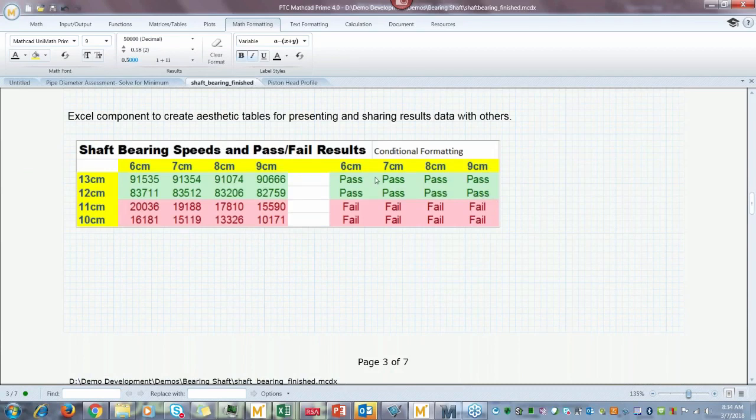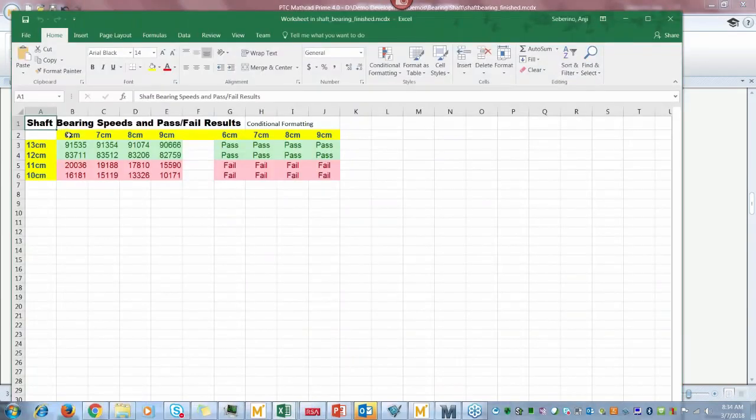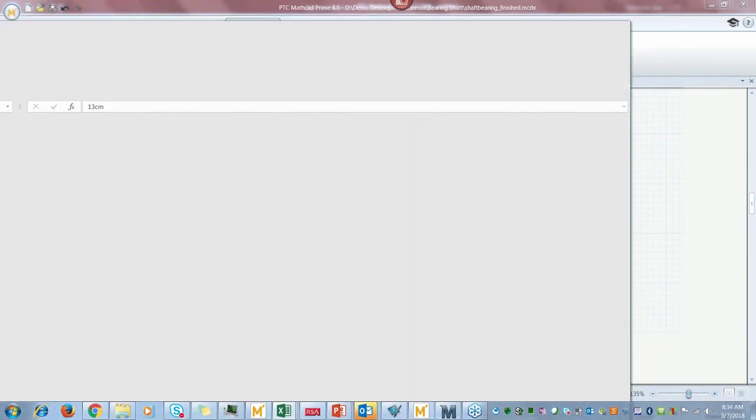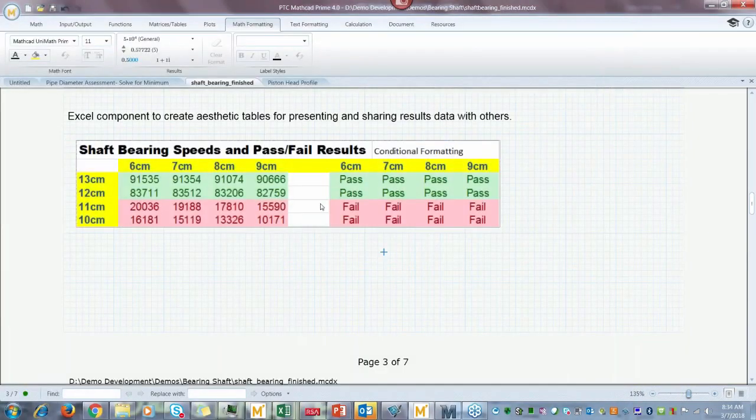And when I did this, here's Excel, I manually wrote in these diameters. But what I really need to do is automate those two so that they update if we change the input table. Okay, but you can see we didn't have to open Excel to see this table update. It just updates. It's all automatic.